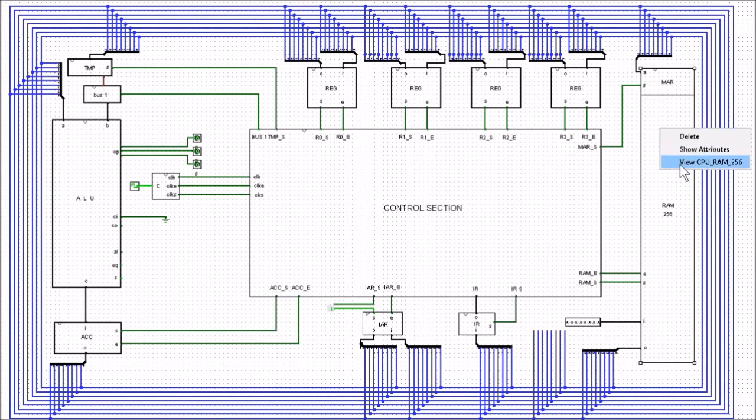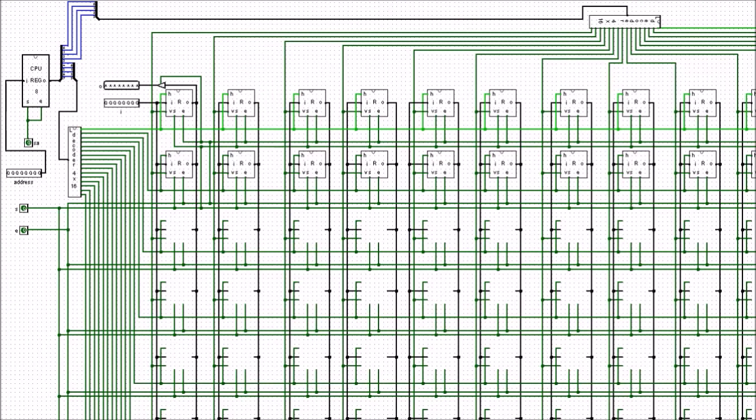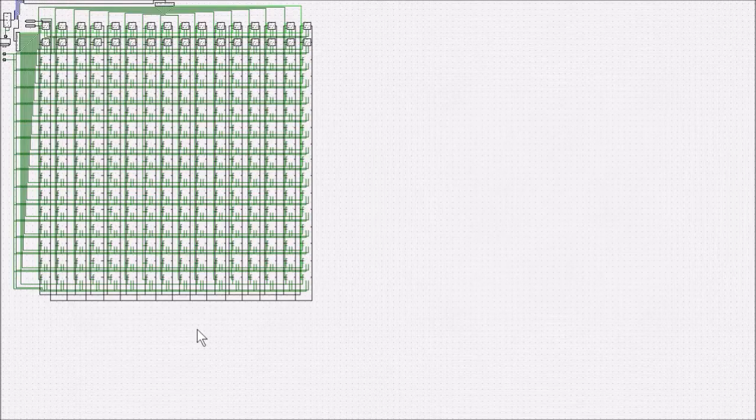So in this instance, if we opened up the RAM and zoomed out, the first address in the RAM is actually this one here. You can see here that the vertical is high and the horizontal is high, and it's choosing this one here. So this is our first address, and it runs 1, 2, 3, 4, 5 up to 16, and then that becomes 17, 18. So when we fetch out an instruction, it runs like this, that way, and then this way.